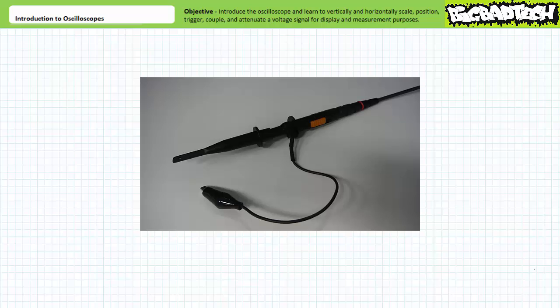Let's return our attention to the grabber and alligator clips. These are the two measurement points, similar to the probes in a voltmeter, between which a voltage differential is measured. Easy, right? Not really. The alligator clip, unless explicitly identified as an oscilloscope featuring isolation, is always directly connected to ground. This means that the simple act of touching something with the alligator clip ground references it.